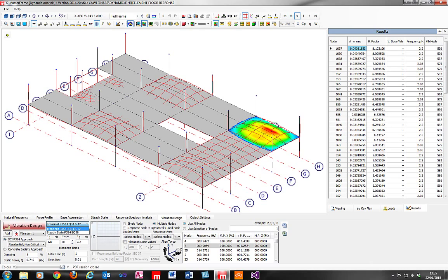In section 2.4.3 of SEI P354, it does give you an example of floors with a frequency above 10 Hertz, where your highest fundamental walking frequency is 2.5 Hertz, as a case whereby you would consider transient design instead of steady state. We ourselves don't give you any warnings as to when you might be using transient or steady state. That is a decision which is entirely in the hands of the engineer, just to make that absolutely clear.